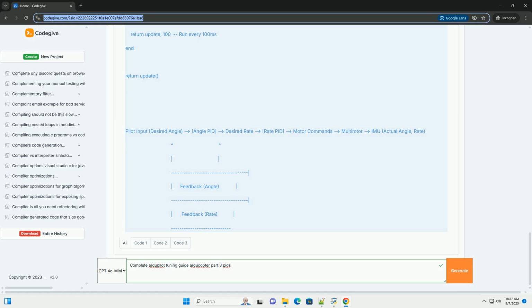Arm the motors and take off in a stable hover. Switch to auto-tune mode, usually Alt_Hold or Loiter. The multi-rotor will start making small, controlled movements to identify the optimal PID gains. Let auto-tune run for several minutes. When auto-tune is finished, it will beep and land automatically.